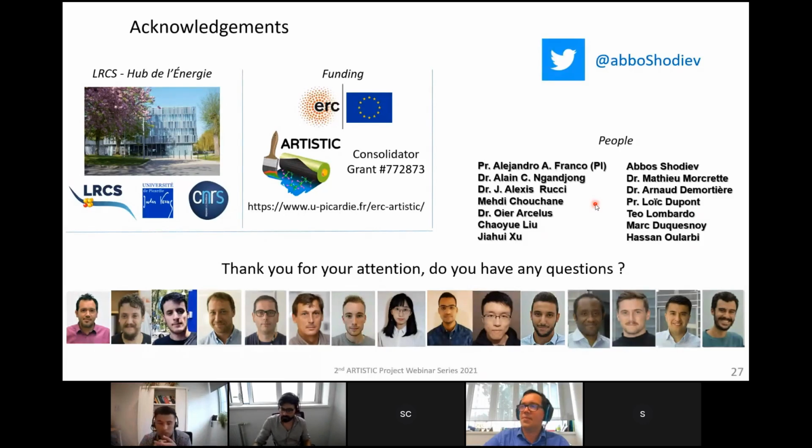But you also have to consider one more assumption in my model: I consider the carbon black domain as a particle. But in reality, it has micro-inhomogeneity and micropores, which can also hold a bit of air trapped inside. So that's a limitation of the technique in the simulation. We are neglecting micropores or nanopores inside the carbon black, which might hold some air as well. Also, you have your swelling aspects, right? Oh yeah, now we have a swelling model, so we see how porosity actually changes after contact with electrolyte, and it's quite fast.